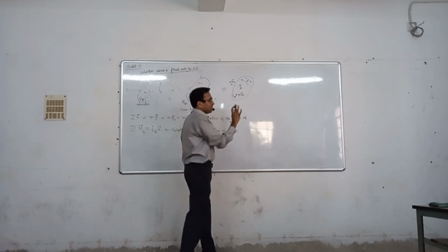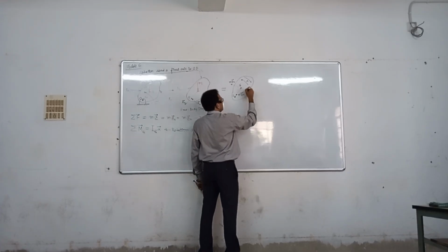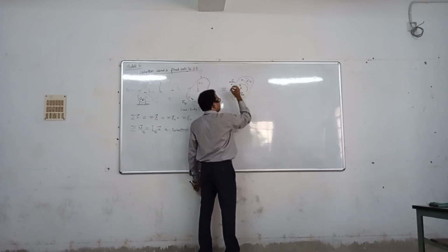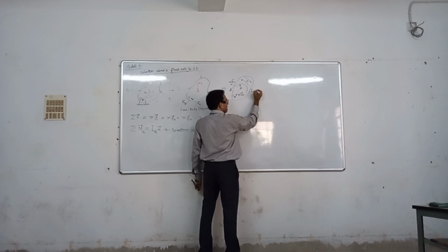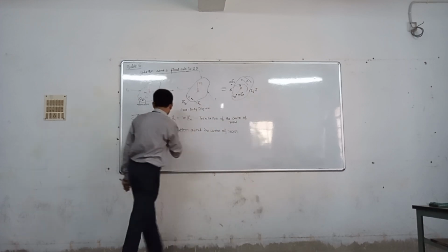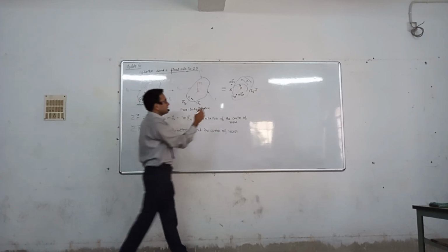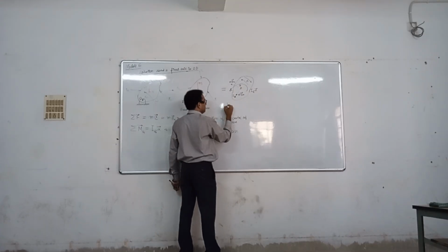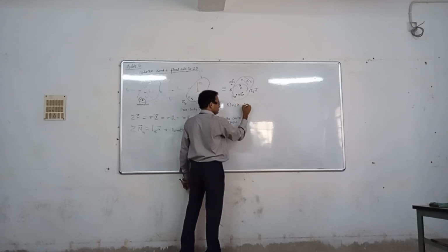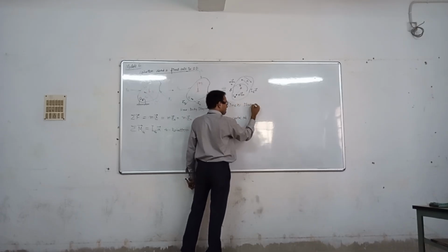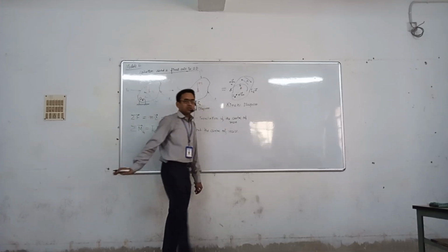Okay. So in any way, say I am showing a rotation about this. So this is the summation of all forces. That means this is the sum of moments of all forces. Therefore, it will be Ig alpha. So this is called the kinetic diagram. Okay, this is the kinetic diagram.